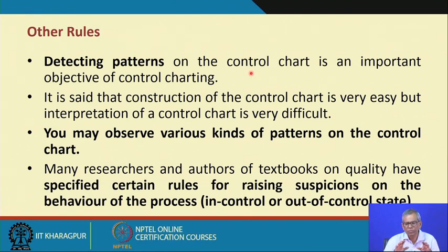Sufficient condition is, even if all the points are plotted within the control limits, make sure that there is a plot pattern you will observe, and when you look at the plot pattern, you do not find any systematic behavior. That means it must be a non-systematic behavior as well as a random pattern. So sometimes if you find randomness in the plotted pattern, and they are all existing within the control limits, you say it's a natural pattern. So what we are asking for in a process which is considered to be in control is, are you getting a natural pattern? Is it okay? So later on we'll discuss the different kinds of patterns. Okay, so we will study it in more depth.